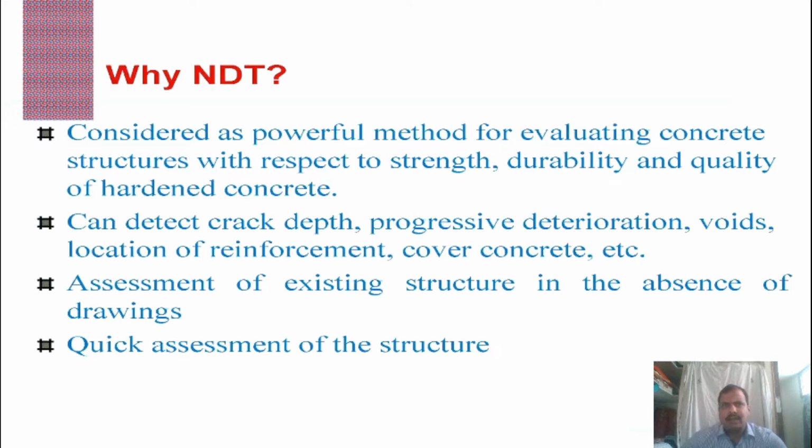In either case, if destructive techniques alone are used, for instance, by removing cores for the compression testing machine, the cost of coring and testing may only allow a relatively small number of tests to be carried out on a large structure, which may be misleading. So NDT can be used in those situations as a primary step prior to subsequent coring.